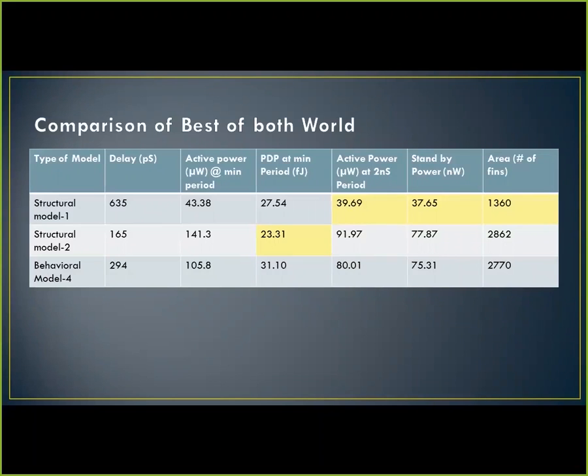And this is a behavioral model which we did, but that didn't give any significant results. One more thing is that we have only considered the static LUT mapping. We could not really use sequential synthesis because for that we needed a clock cycle. So we got all the results on the basis of static LUT mapping.